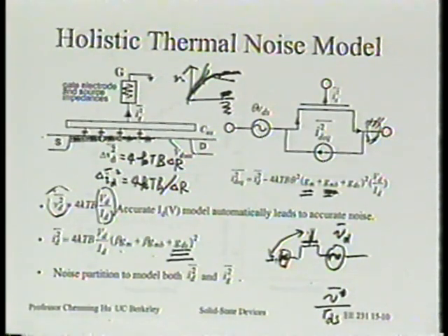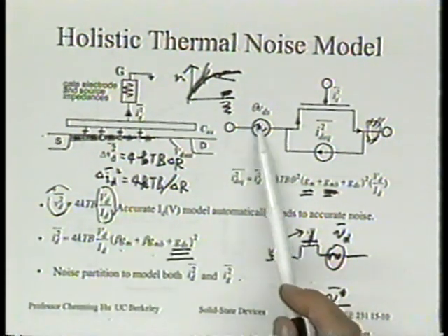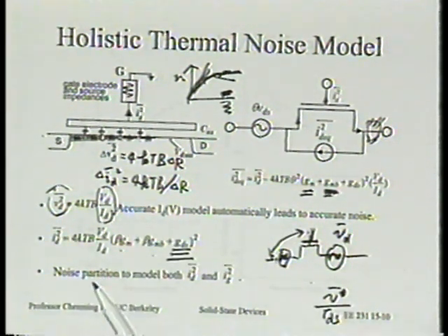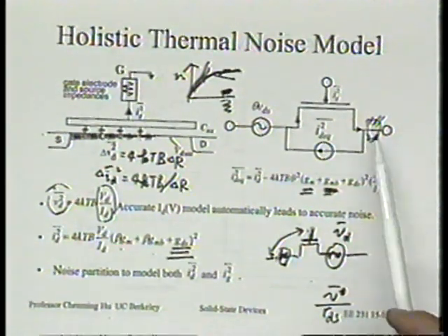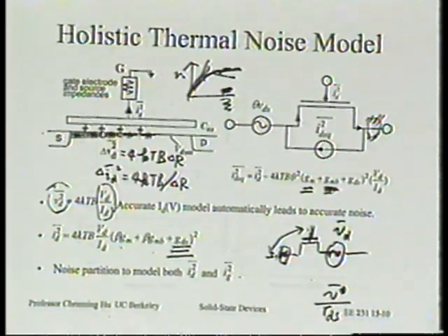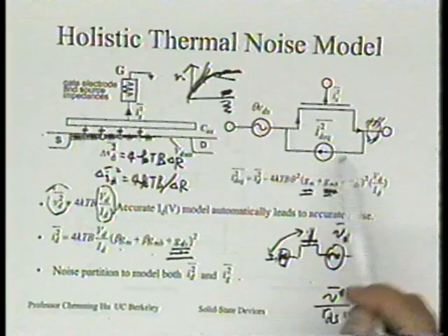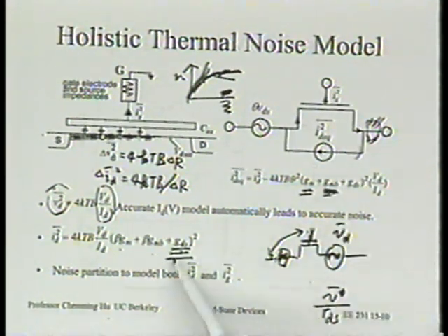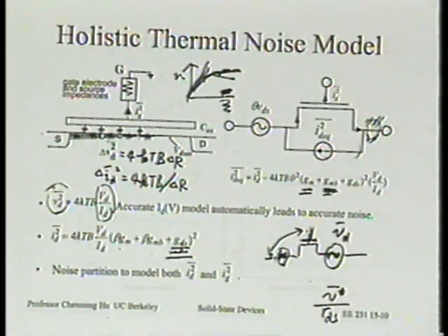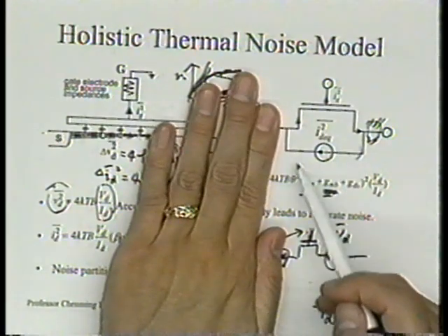So conceptually, we just divide the noise voltage into two parts. One part we put in the source. One part, effectively, we can say we put in the drain. We don't even put it in the drain, you will see later for other reasons. Whatever is needed, we just translate that into the additional noise current. By the way, this is a standard way designers like to use.